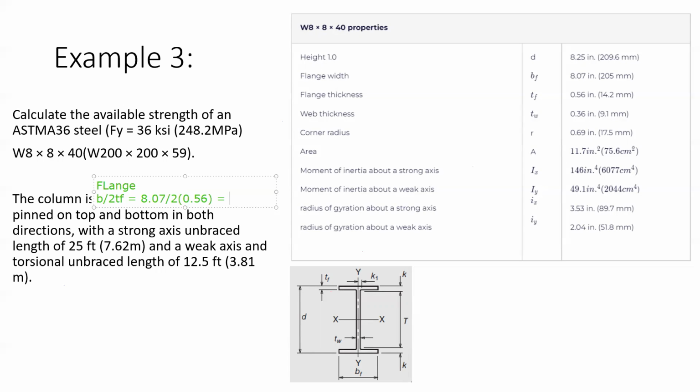7.205. Let's check naman if it's less than, equal, or greater than 0.56 times the square root of E over Fy.